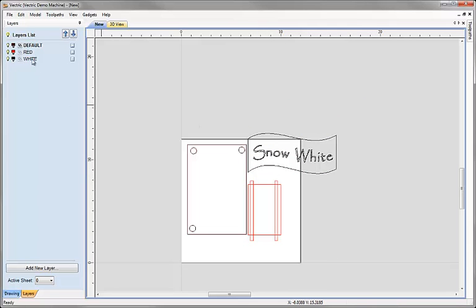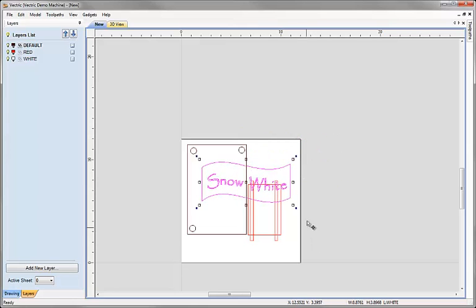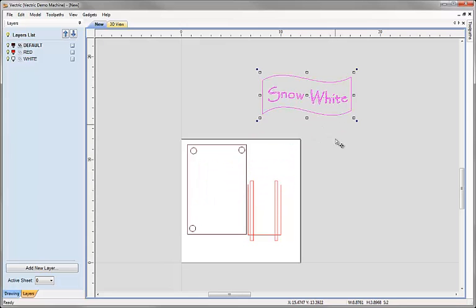Essentially, one of the filters that we apply to the imported DXF is to pick out white layers, and actually we actively convert those to be black. The reason is simple: if I take this layer and make it white deliberately, which you can do in the software, you'll see that now when it's not selected, it's extremely difficult over the white material block to see this layer at all. So it's apparently invisible. To avoid that really common hazard, white layers that are imported will be made black. You can, as I've just demonstrated, make them white again if you so wish, but at least you'll be aware of what's going on.